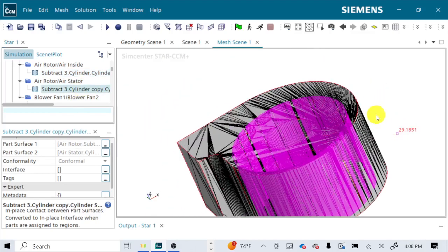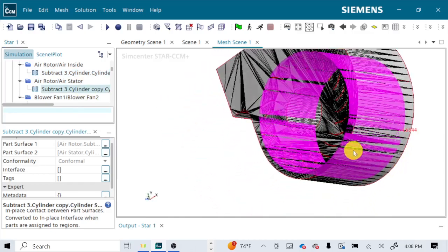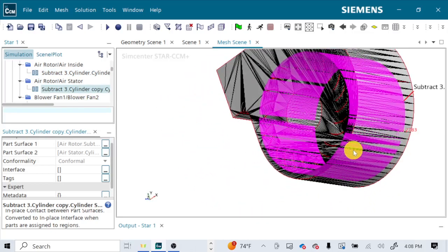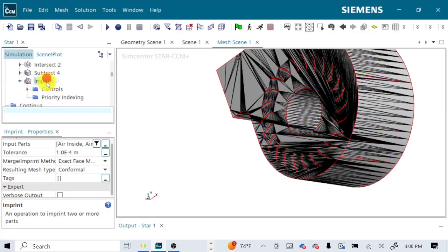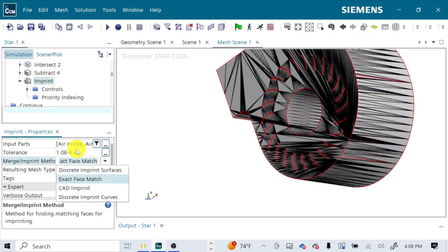Ditto the outside. It's got all these random lines, it almost looks like somebody wrapped a barcode around a cylinder. Doesn't make very much sense. So what I did to break this is I told it only create an imprint, a contact, where they are exactly matching, which means it was much more precise than it needed to be.